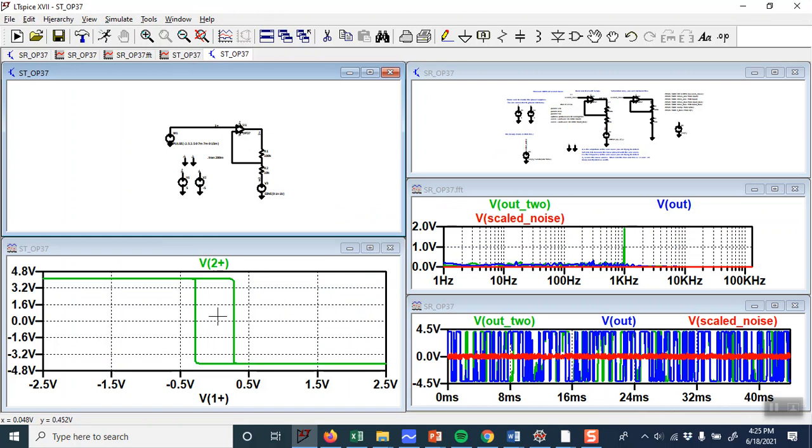Now you might think you have to change the hysteresis width with these voltages, but if you look at the equations in the lab manual and on Wikipedia, I can change these switch positions by changing the power supplies. Now the maximum power supply is plus or minus 5, but if I lower them, I can make these smaller.